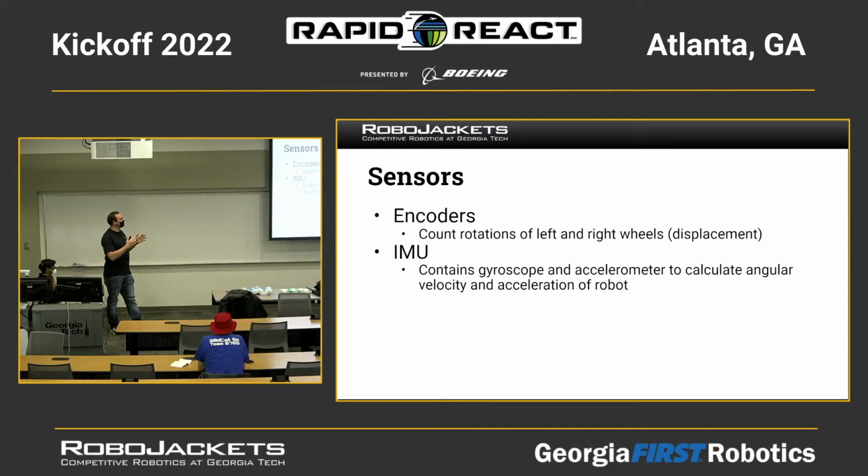So the sensors we're going to use are encoders. We're going to count the number of ticks on a left wheel or a right wheel. So essentially how far we've traveled on each one of those wheels. We have our IMU that can give us accelerations as well as, my understanding is you guys get out yaw directly, so like the orientation of your robot on the XY plane. Usually you don't get that, you usually have to integrate for it, but it's fine. So use the gyroscope. But what are the important things about these sensors?